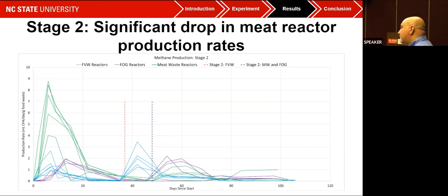And the Hezhou strategy specifically is what we're trying to find. We're trying to find easy methods to heat up the reactor somehow, and by doing that for a short period of time, the effects can last for about 60 days, which we think could be effective. But of course, there needs to be a lot of pilot-scale or even full-scale study done after the lab-scale study has been proven effective.